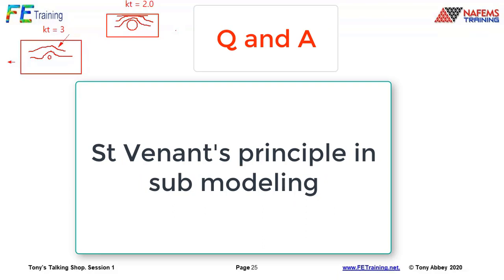Karma says, Saint-Venant's principle is used in submodeling techniques, which is what we had essentially with that needle. And then he makes a comment: one tricky part is deciding the boundaries of the submodel so we don't get the boundary effect. Yes, exactly. Do you have any tips on how to decide the proper boundaries of the submodel? So it's a distance thing.